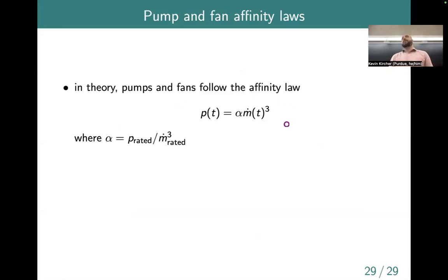So if you do kinetic modeling, I guess, of say air flowing through a fan, you find that the electric power, the work input to the fan, is proportional with some constant alpha to the mass flow rate cubed. So we get roughly cubic power dependence. And here the coefficient alpha, typically you can find a fan if you can find its model number.